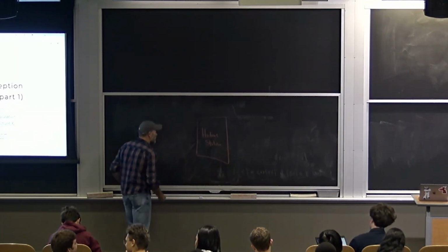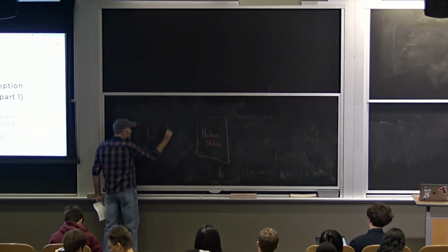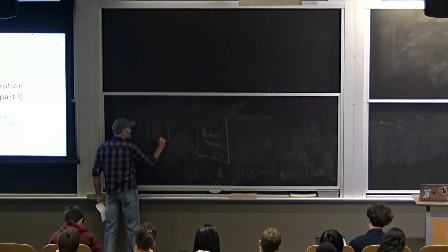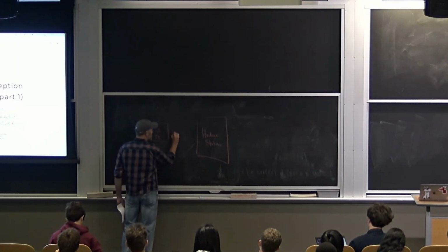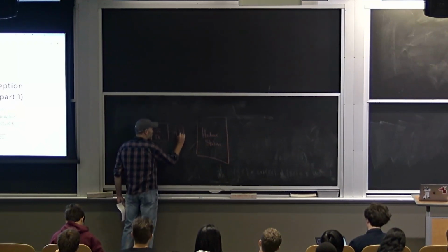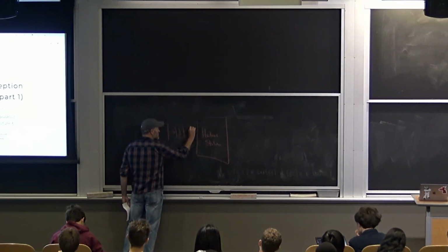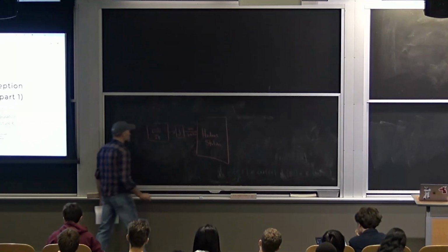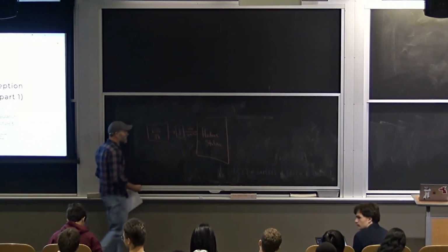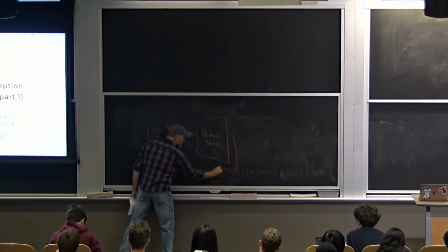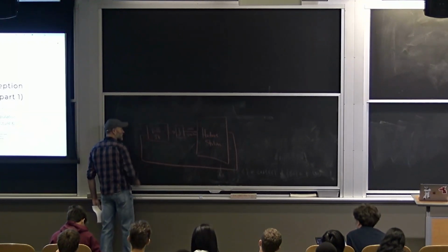And we built on top of that our differential inverse kinematics block, which, after some integration, sent us iiwa commands, iiwa positions. The diff-ik block needed to know the current iiwa state. So we had an important line here.